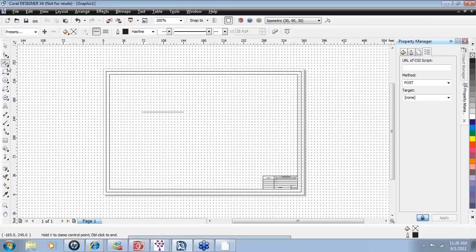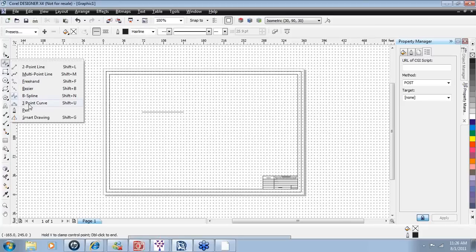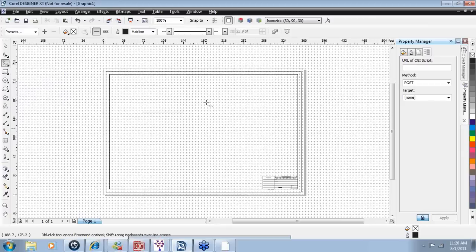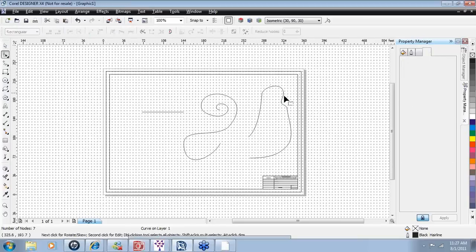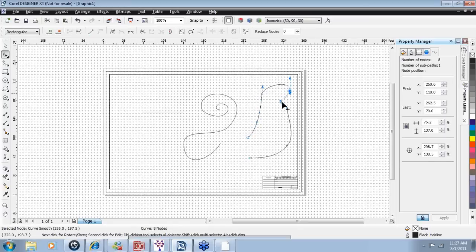One additional line tool that I'd like to share with you before we work with our imported site plan is the freehand curve. If you don't want to lose the freedom that you had with pen and paper, the freehand curve is going to be your tool. And just watch, I can freeform any lines. Even if I'm a little bit jagged, a little bit shaky, it's going to automatically smooth that line out for me. We can go back in, double tap on this line, and it does give you some control points where we can make some adjustments to this line as needed.